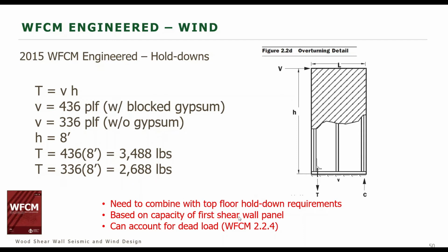And again, we have the same notes for combining it with the top floor hold down requirements. You can account for dead load offset in chapter 2. There is some language that will allow for that in 224. We did not do it in this example, but you are allowed to do it if you're using chapter 2.